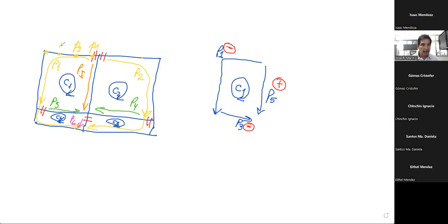And then we specify point three. If the thickness is the same, then the thickness at this point is going to be equal to the thickness at that point. In a real ship, in this part here, the thickness is going to be a little bit larger than in this part. So the thickness associated with point 4 is going to be a little bit larger than the values at points 2 and 3.